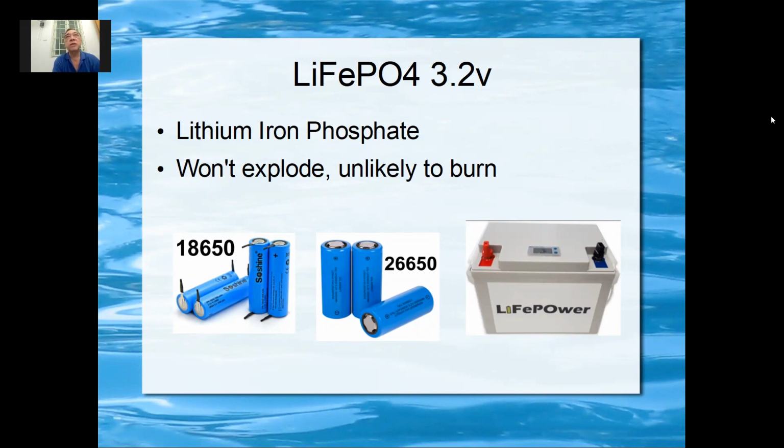You will get into problems, because when one of the batteries is weak, this battery cannot be fully charged, and it will remain not fully charged forever. It's just like you put 4 people on a table and then you provide the food. The stronger one will always eat most of the food.